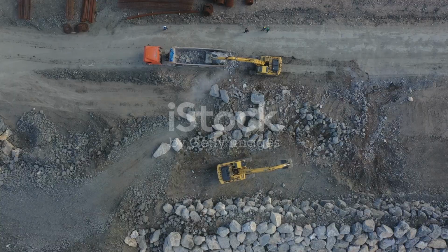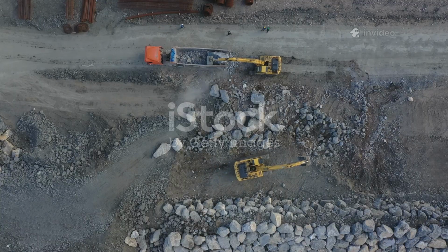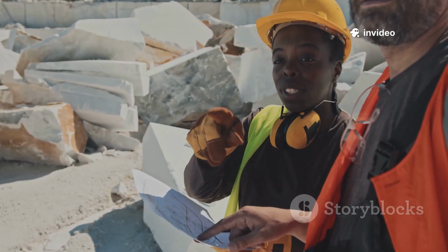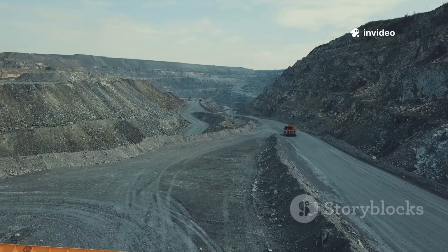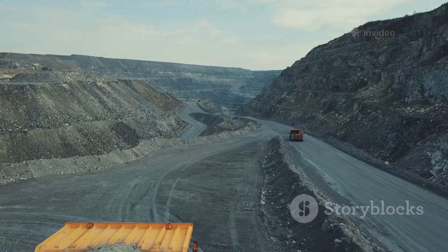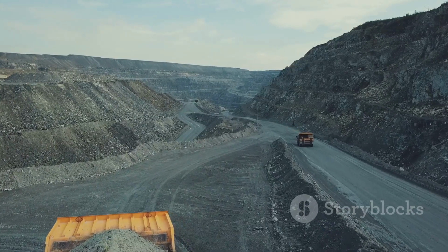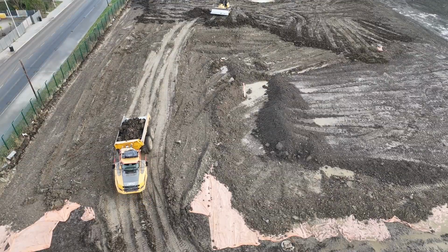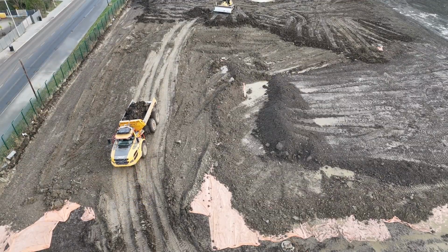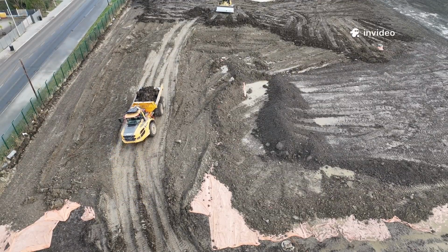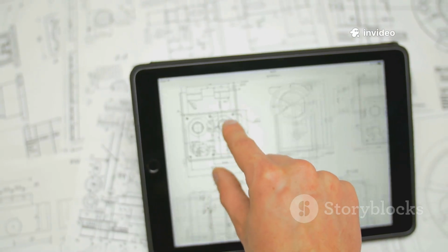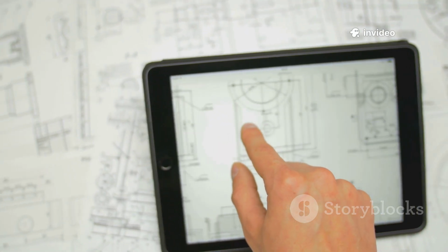But what if you have to move dirt farther than the free haul distance? That's called overhaul, and it costs extra. Overhaul is any dirt hauled beyond the free haul limit, and contractors charge for every extra foot. The cost is measured in station yards: 1 cubic yard moved 100 feet beyond free haul. The mass haul diagram shows exactly how much overhaul is needed and where.